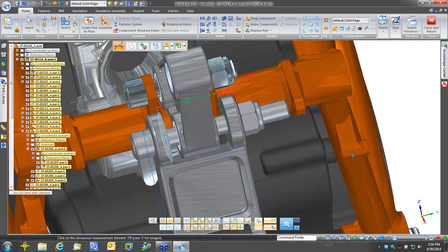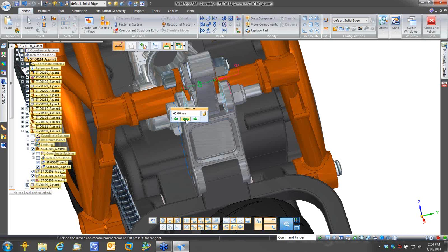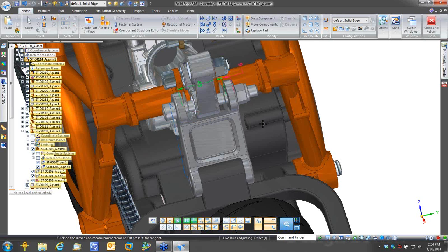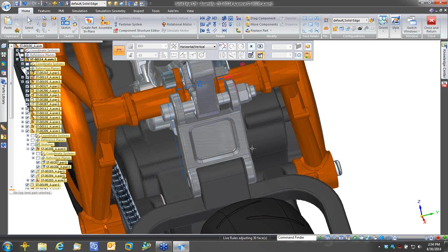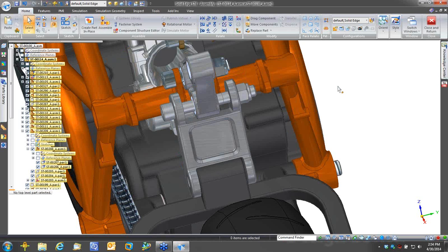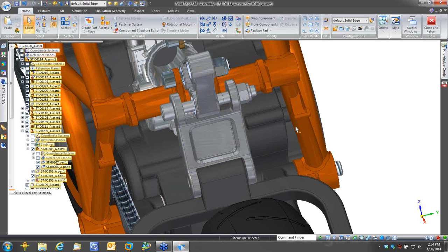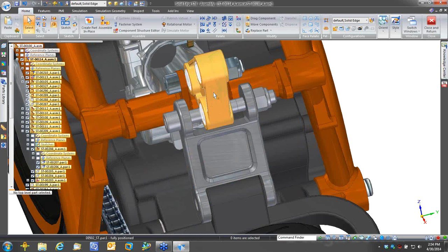So right here, after placing that dimension, I can come in and I can make changes to that value to eliminate that interference. So maybe I need it to be maybe 52 and put a millimeter clearance on either side. And right here from the top level assembly, I've made those changes. Now, by changing the width to eliminate that interference, I've got a lot of slop now between our mounting arm and our housing here for the bearings.